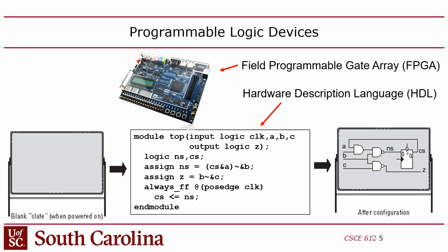And then in between those gates, you have wires that are all connected through switch boxes, right? So you can configure those switch boxes like an old-timey telephone operator, who would put the wires in to establish connections. It's basically what happens. You can create arbitrary connections between those gates. So you could take the output of a gate and connect it to one or more inputs of another gate, inside that array. That's basically how it works.